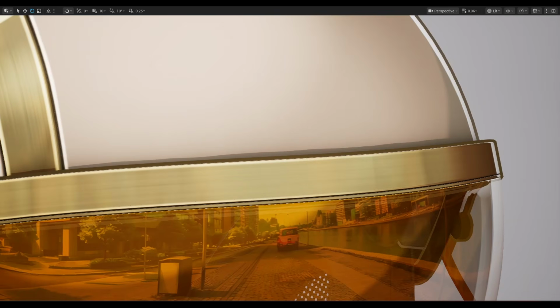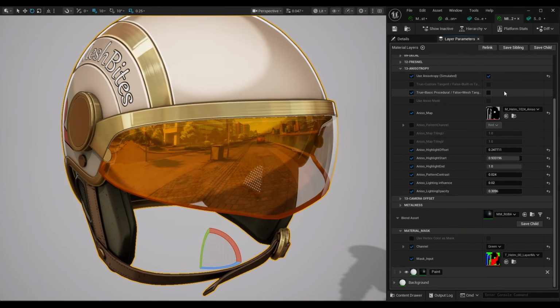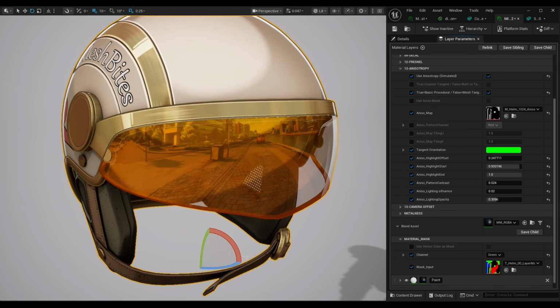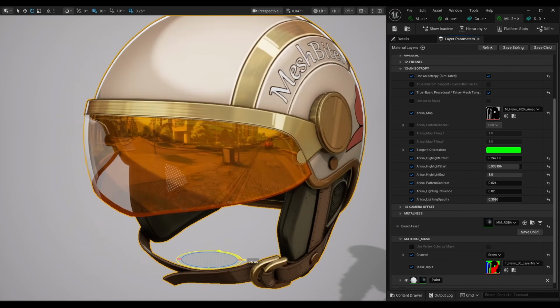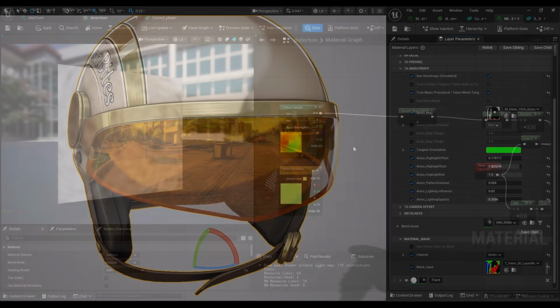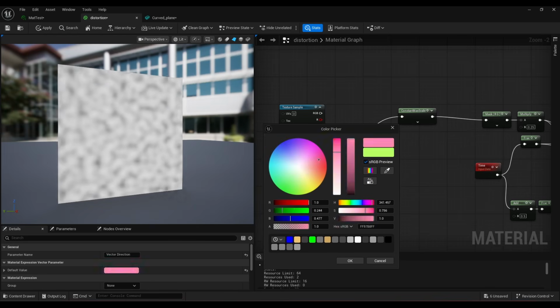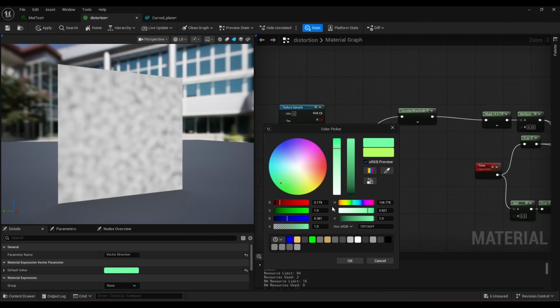Mirrored or overlapping UVs can also create problems. Since tangent direction depends on UV orientation, mirrored UV islands often produce visible seams because the tangent direction flips across the symmetry line. If modifying the model is not an option and you still want to reduce these artifacts, another approach is to use a procedural tangent direction inside the shader. This ignores the mesh tangents and instead uses a flat, consistent direction across the surface. However, this also means the entire surface shares the same flow direction, which may not always produce the desired result.